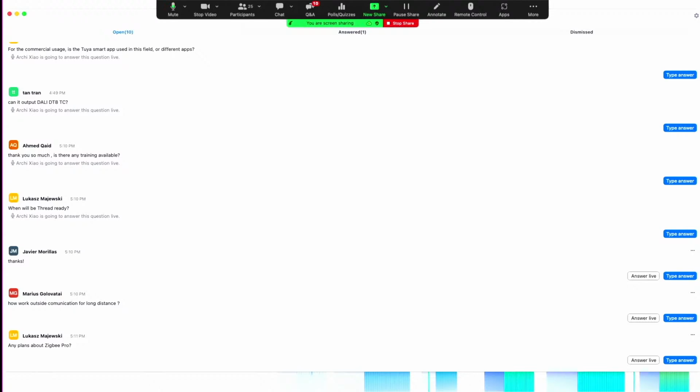So for the long distance, from the protocol side, ZigBee is longer range than Bluetooth, but some applications would like to have a longer distance than ZigBee. Now we are working on another protocol called Wi-SUN. It will cover around 1 to 2 kilometers, and for outdoor applications, they can try NB-IoT, Cat1, Cat LT solutions for the long distance. I see. Frank's example earlier on at the golf course was a great one for that as well, using the puck.